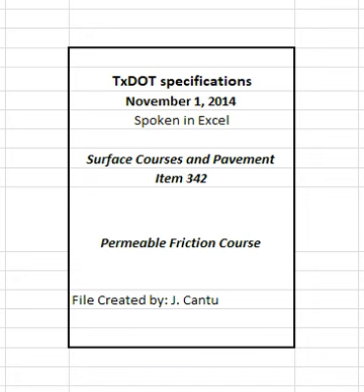Provide output data from the thermal imaging system to demonstrate to the engineer that no recurring severe thermal segregation exists in accordance with Section 342.4.7.3.1.2, Thermal Imaging System.